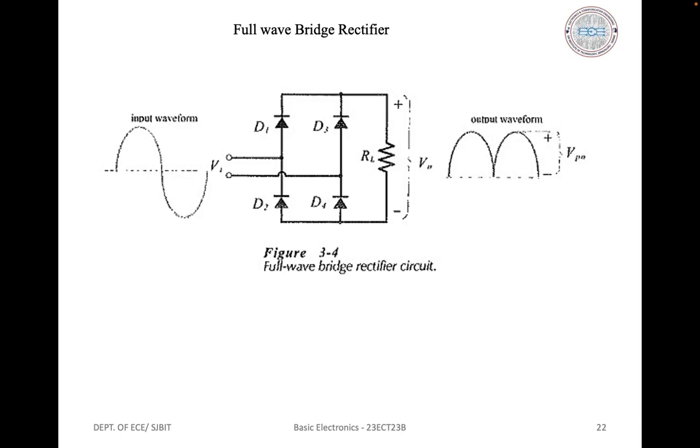voltages. A full wave bridge rectifier circuit always requires that the input be derived from a transformer that provides DC isolation from the supply. The circuit will not function correctly if one of its input terminals is grounded. However, given the required DC isolation between supply and output, either output terminal may be grounded to provide a positive or negative output voltage.